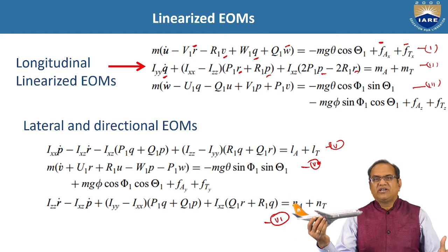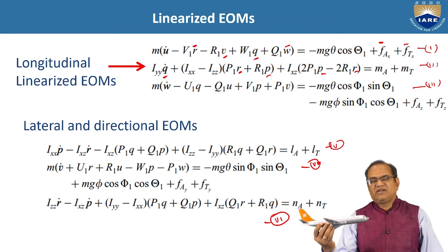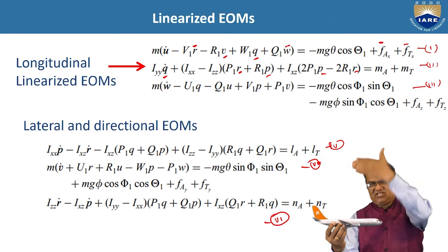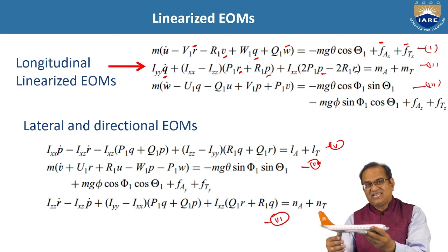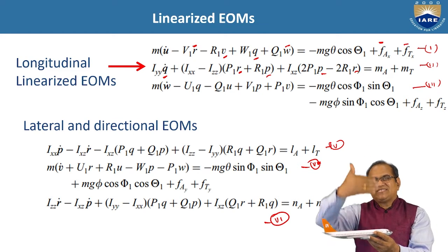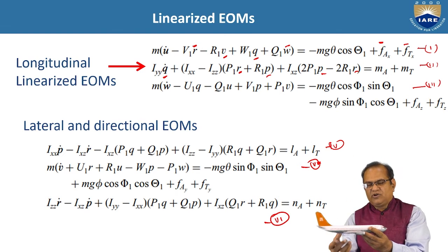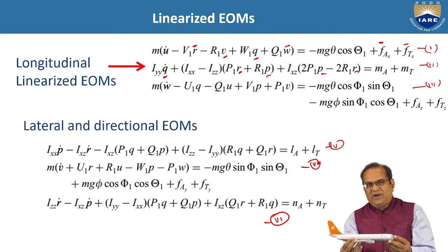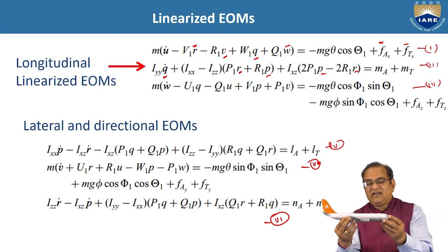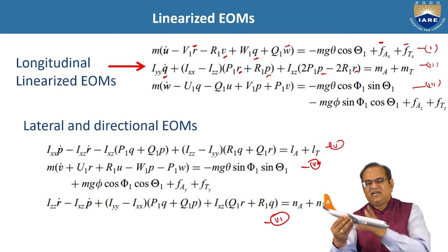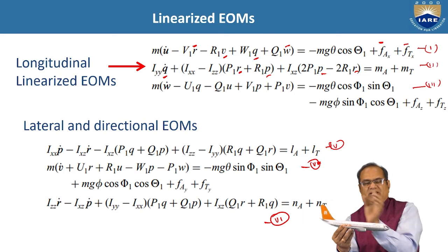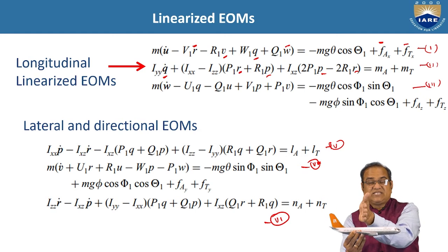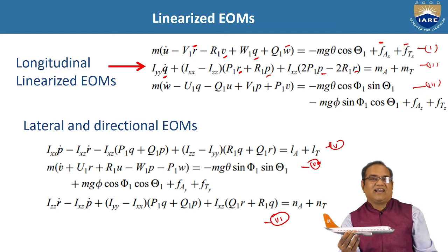Once we talk about longitudinal aircraft static stability, so the motion in X, this is X and this is the Z. If the motion is taking place in the XZ plane, it may go forward or rear, that is the X. It may go up and down, it is called plunging, and there is pitching. This is the Y, and it is moving in the X and Z plane, so this is with respect to the Y axis or the lateral axis.